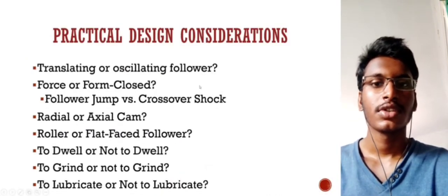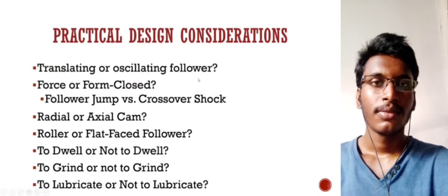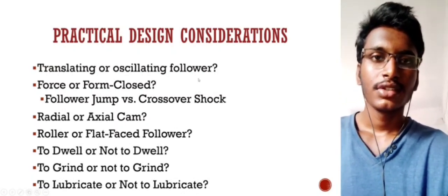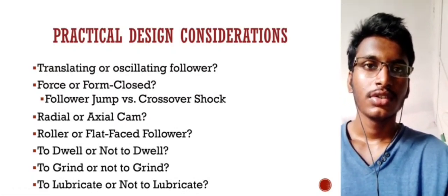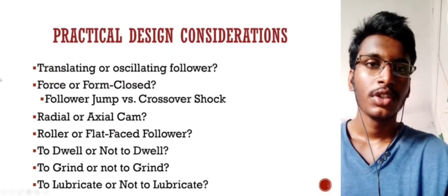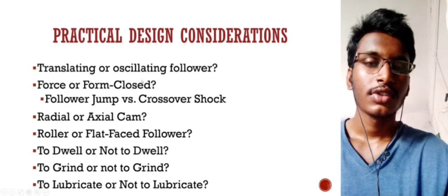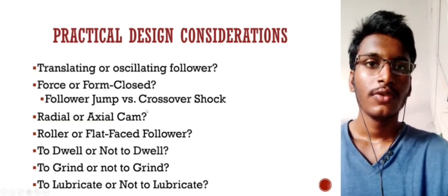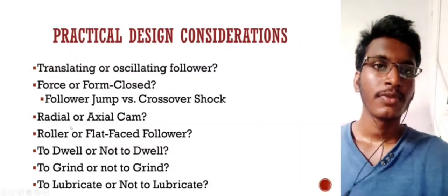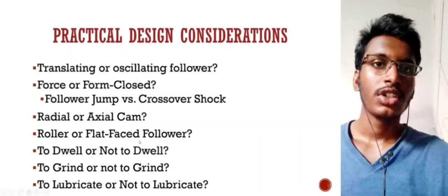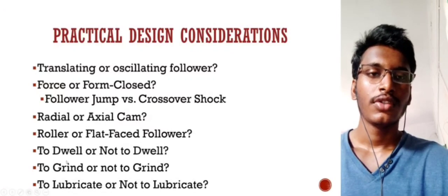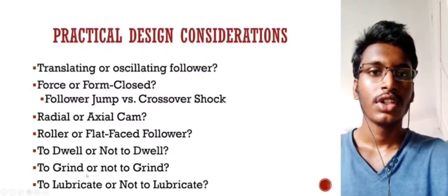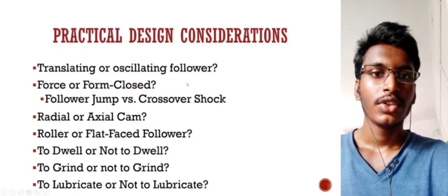Next, the practical design considerations. Before designing a CAM, we should check this; it looks like a checklist for designing a CAM. They are: translating or oscillating follower, force or form closed follower, jump versus crossover shock, radial or axial cam, roller or flat faced follower or mushroom follower, to dwell or not to dwell, to grind or not to grind, to lubricate or not to lubricate.